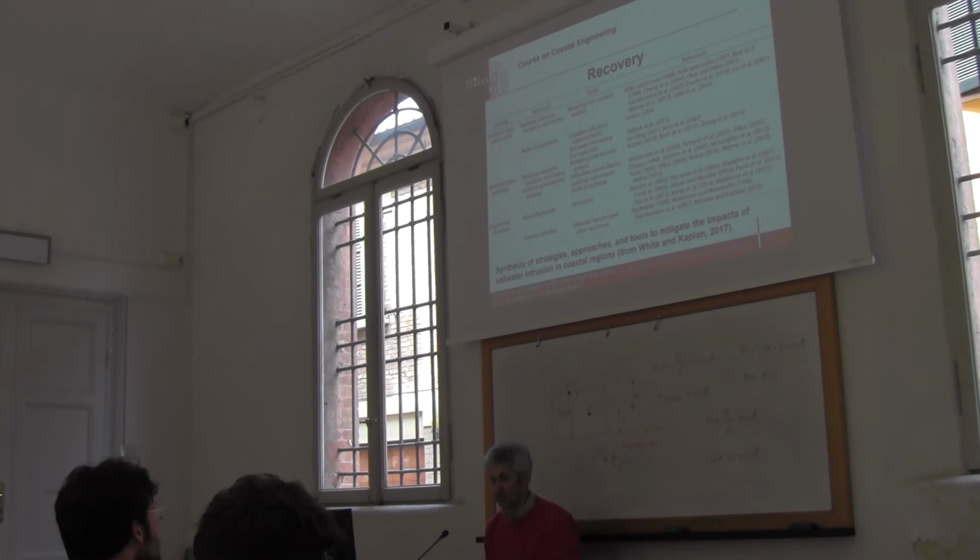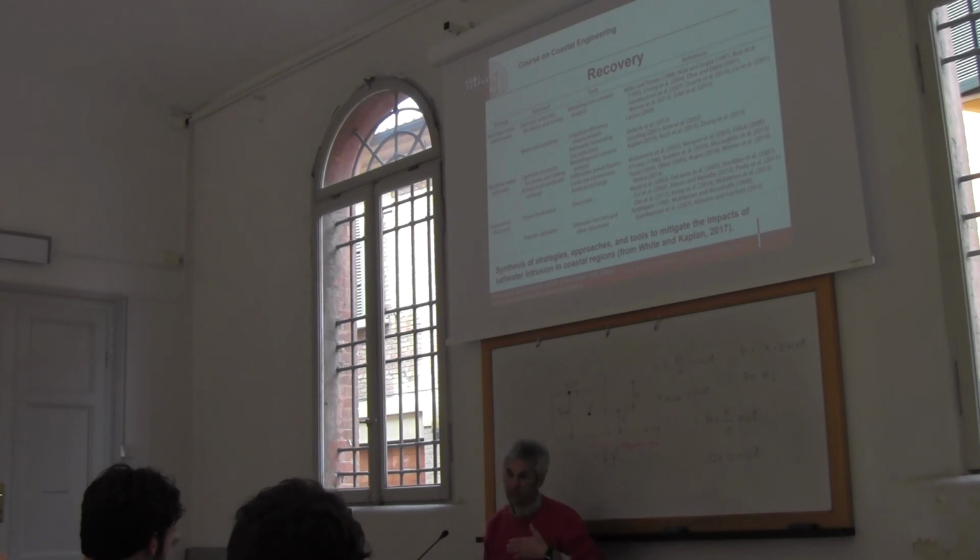And first, we can act on water withdrawals, because typically the main driver, the main cause of saltwater intrusion is groundwater withdrawal. It's not sea level rise, it's not climate change. It may be a tsunami, but it's very rare, very infrequent. What frequently happens is that we take water from the wells and water demand increases, so we take more and more water from the wells, and at a certain point we realize that the water in the well is saline, is salted, and therefore we need to go back.